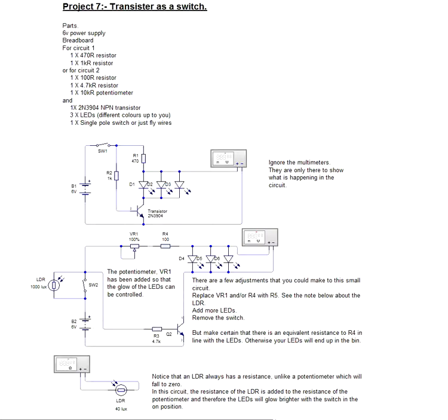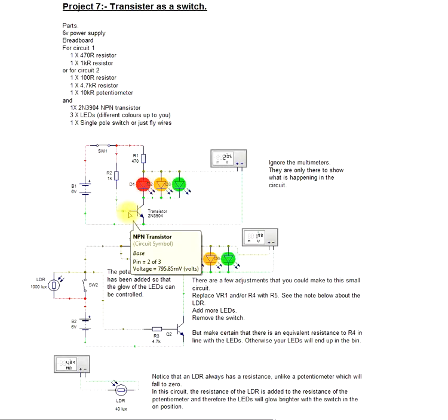There are many applications for a transistor, but this particular one is basically using it to switch another part of a circuit. What it does, well, I'll show you, that's the easiest way. If we turn the power on to the circuit, it allows a small voltage coming through here, and then turns the transistor switch on, and it will join that to that, and it will help light the LEDs.